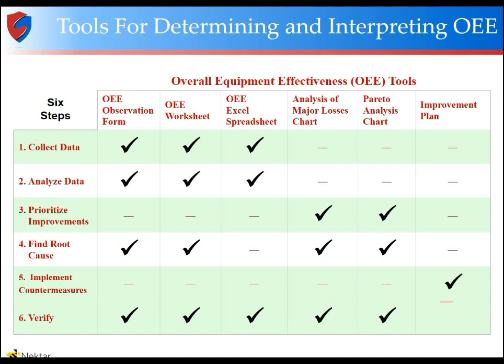Okay, here's some tools that we'll use to analyze our OEE. So we got those 6 steps that I went over: collect the data, analyze the data, prioritize the improvements, find the root cause, implement our countermeasures, and then verify. Constantly measure and monitor your OEE.